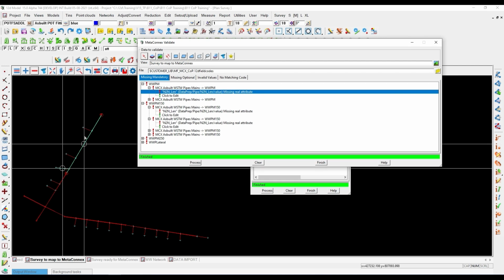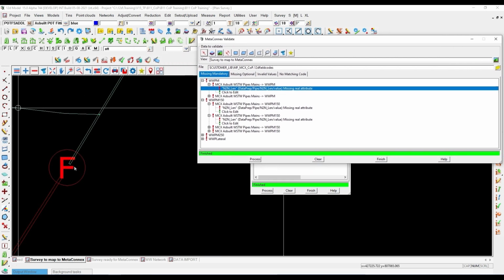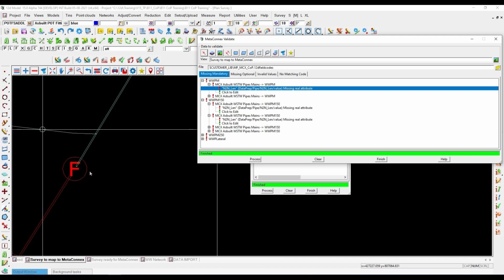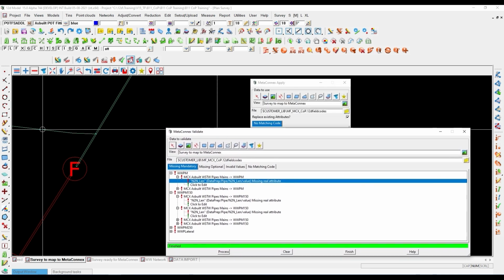These are node to node length, where the GIS people want to have the true virtual pipe, but join this point to the center of the chamber. It's not correct. It's not the true length or grade of the pipe as the surveyors and the engineers want, but that's the way the GIS wants it. So I've got another little tool in here, which is called node to node distance.